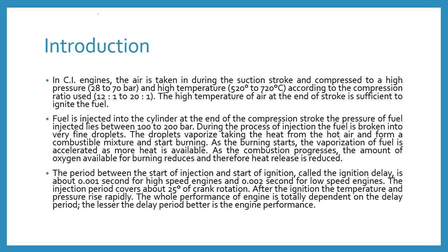Thus it can be said that during compression of air in the engine cylinder the temperature of the air goes up, so that when the fuel in the form of a fine spray comes in contact with this hot air it ignites, and no other external means of ignition is required. For that reason the diesel engine is known as a compression ignition engine.